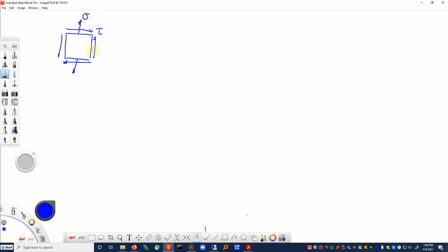It is possible with additional controls and test configurations to get a stress in the hoop direction. If you did internal and/or external pressure, you can vary the hoop stress, so you could get two directions of sigma and a direction of tau. We're going to see a little bit later, when we look at a paper of Daryl Sosey's, how this can influence the cracking behavior in a material when you add that additional hoop stress to it.